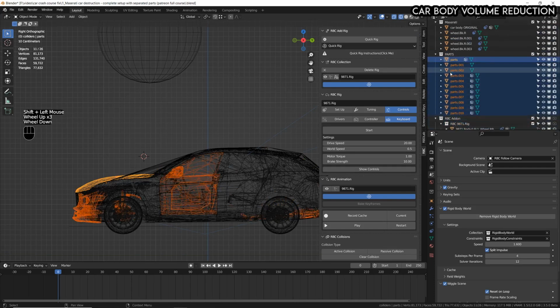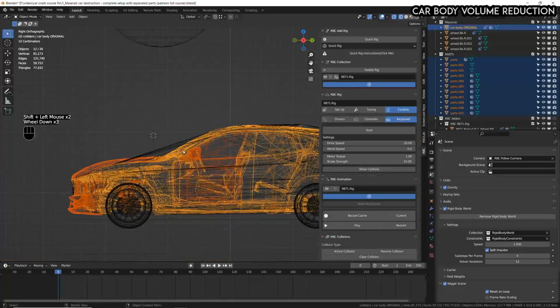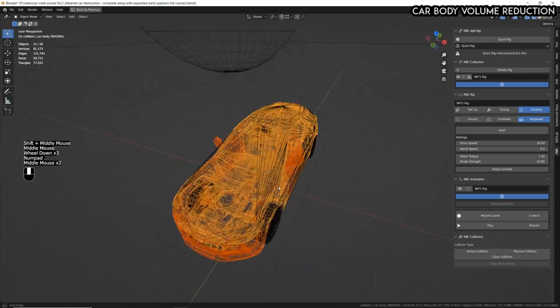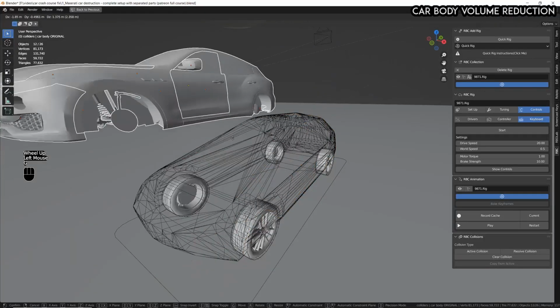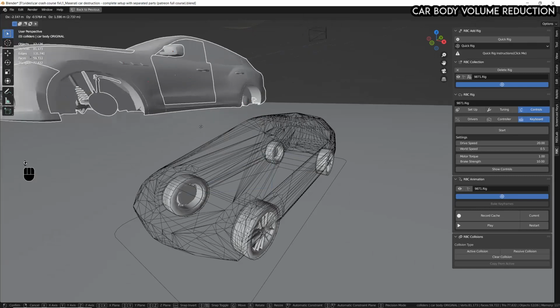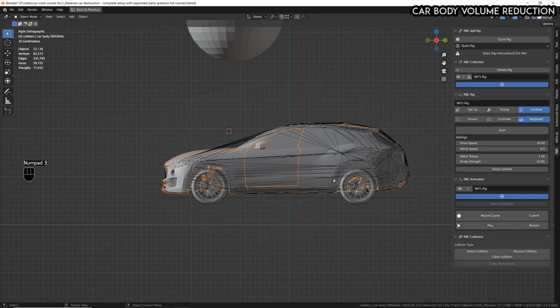and then holding Shift as a last element, only as a last element is very important, from the 3D viewport, hold Shift and select also the body of the car. Alright? So you should see something like this. If you did it correctly, you should have selected all the parts of the car except the wheels. And if you try to move it, you can actually check that you did it right. And you can press ESC to abort this operation.